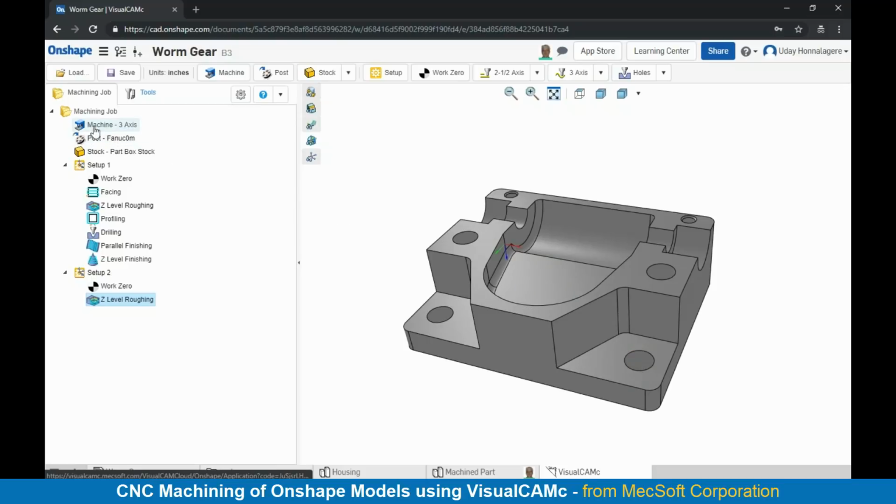So if you define the machine tool as a 4-axis, and if you're using a 4-axis machine where the part can be rotated on a rotary table, yes, it will output the rotation angles to rotate the table or the rotary axis by 180 degrees in this particular case. If you define the machine tool as a 5-axis machine tool, then each of the setups will output the orientation to get to that. If you only have a 3-axis machine tool, the user would have to refixture the part to manually orient it, and then you can basically post-process each setup out as a separate file.